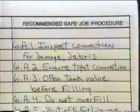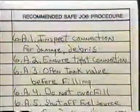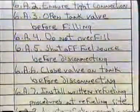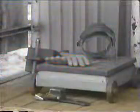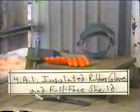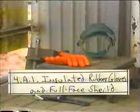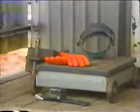All the other recommendations are an effort to control hazards. Inspecting the equipment before use and following safe procedures during the filling operation minimize the chances of a leak or a fire. Recommending the use of the proper gloves in step 4 is another example of controlling a hazard. Personal protective equipment is often the only alternative when a particular hazard cannot be eliminated.